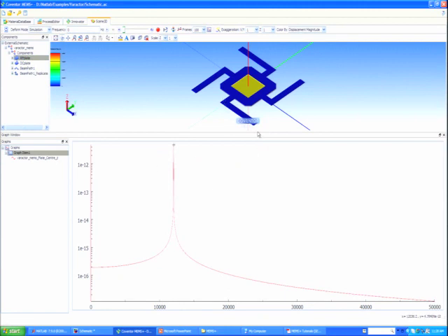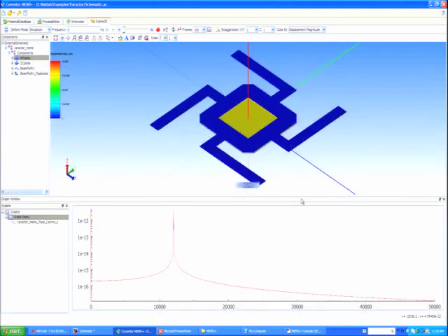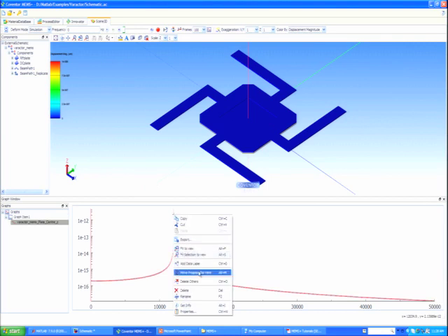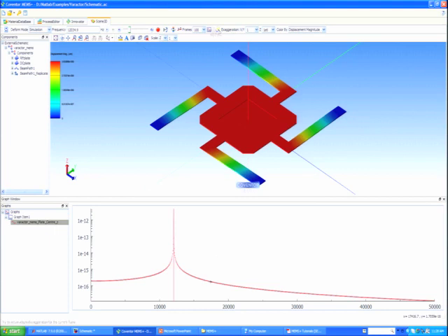But now I have an AC analysis here. Now in MATLAB, this is what you would see. It's like a Bode plot type output. This is okay, but I want a physical image of what exactly is going on. That's why I look at the 3D results. So I can move the progress bar here, and then I can look at, okay, that's my first mode, and sure enough, that's what you would expect to see for a device that's fixed on all four sides. The thing is moving up and down. Okay, so in all of 30 seconds, we've got a good result from here.